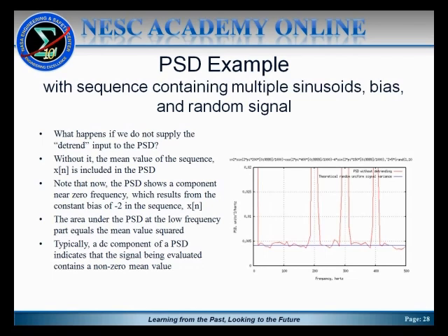the discrete Fourier transforms. And so what you see now in this plot, again, which is expanded out, but you'll notice now down around zero frequency, you see a spike in the red line from the PSD, which wasn't there previously. So what it's done is taking that mean value that has not been removed in this example and applied it to zero frequency.